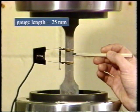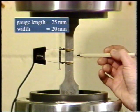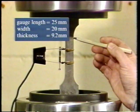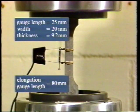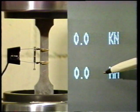You need to know the cross-sectional dimensions of the test piece. It's 20.0mm wide, and it's 9.2mm thick. We've put top marks at 80mm spaces so that we can measure the elongation afterwards. The output from the extensometer is coming up here on the screen on the displacement marker.